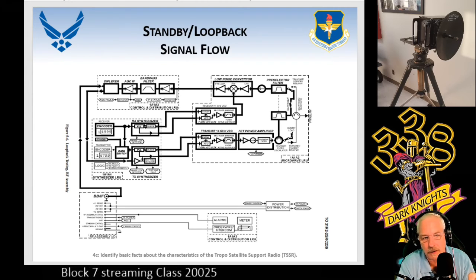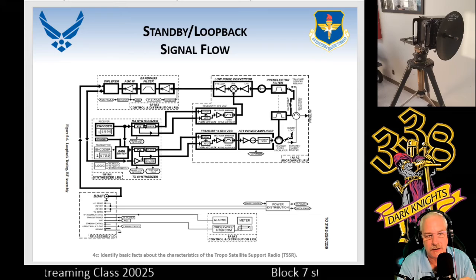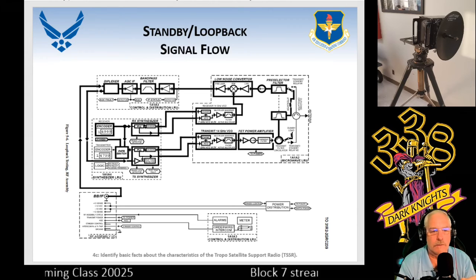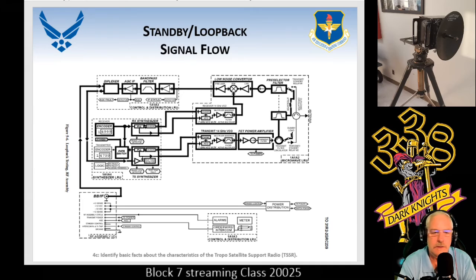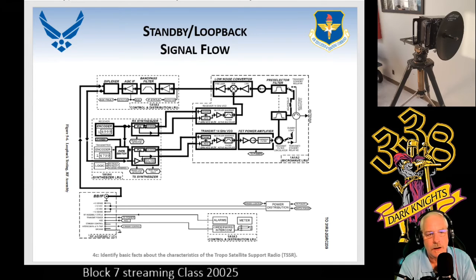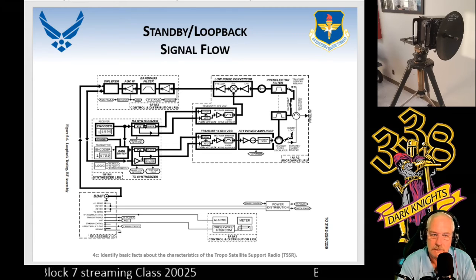Let's go into the microwave LRU. Right above that, where the microwave LRU is making that statement, the 1A1, A2 section, the bottom right-hand corner of it, if you look right above it, you'll see that the standby operate switch is no longer in the operate position, but in the standby position. Now, when you come out of that harmonic filter, you have approximately 316 milliwatts or 25 dB of gain or 25 dB of signal strength. You don't want this to go right into the receive section. Why? It'll burn it up.